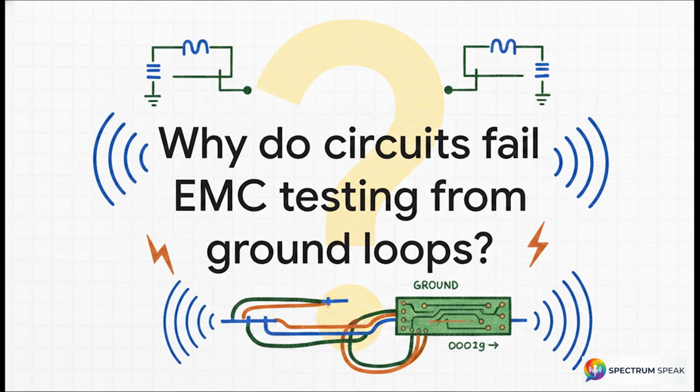Let's tackle this core problem right out of the gate. Why the invisible noise? Well, to understand how this happens, we need to look past the surface of your CAD tools. The truth is, a schematic only tells half the story. It assumes ground is this magical, zero-ohm, perfect sink. But out there in physical reality, your ground paths, the actual copper traces, the vias, the wires, those are what completely dictate whether your product passes or fails regulatory compliance.